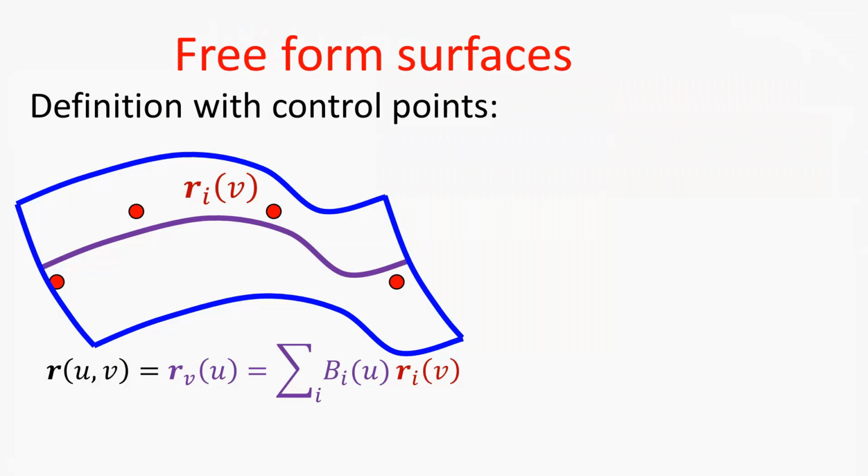So far we traced back the definition of surfaces to the definition of curves, and these curves can be analytically defined curves or free-form curves specified, for example, with the strategy of Catmull-Rom splines, Bézier curves, Lagrange interpolation curves, anything we want. Free-form curves are defined by control points. Using this approach, we can also say that all surface definitions will require the specification of control points from which the curves and finally the surfaces are built.